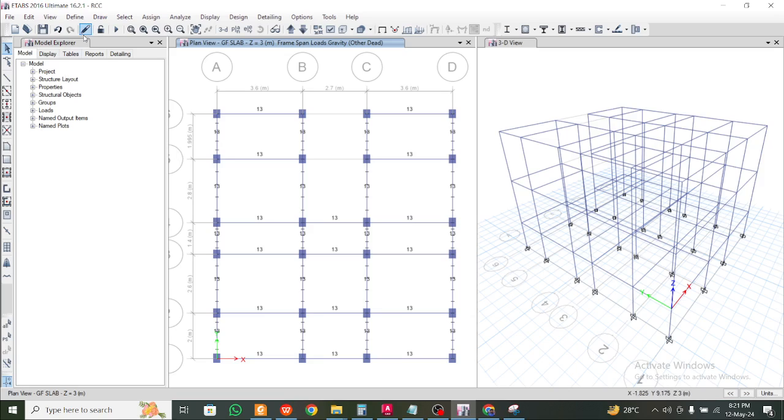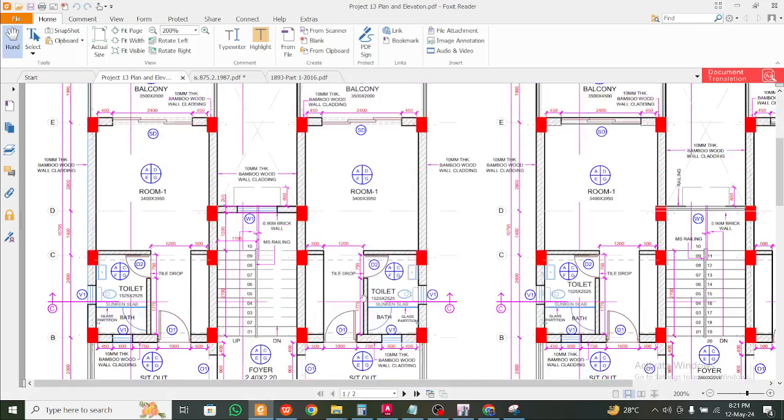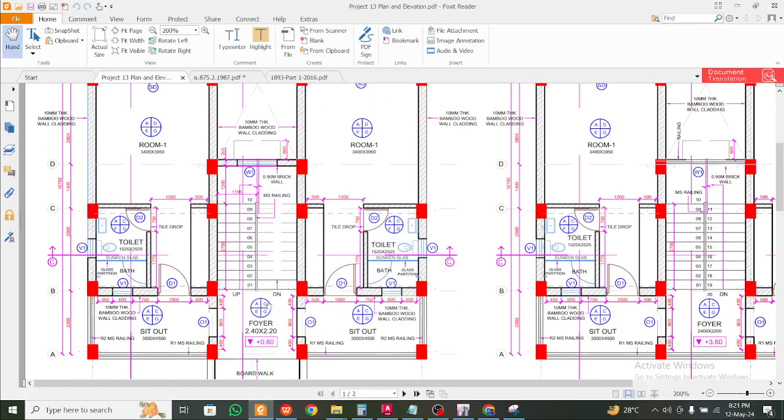Okay, so we go here, I think for rectangular slabs. So I have to just check the staircase location in the plan. So the staircase location is this. Apart from this, every position there will be a slab. I think in this position also, if we avoid the slab, then it's good. No, in this position we have to give the slab, and only in these two grids the slab will not be present.